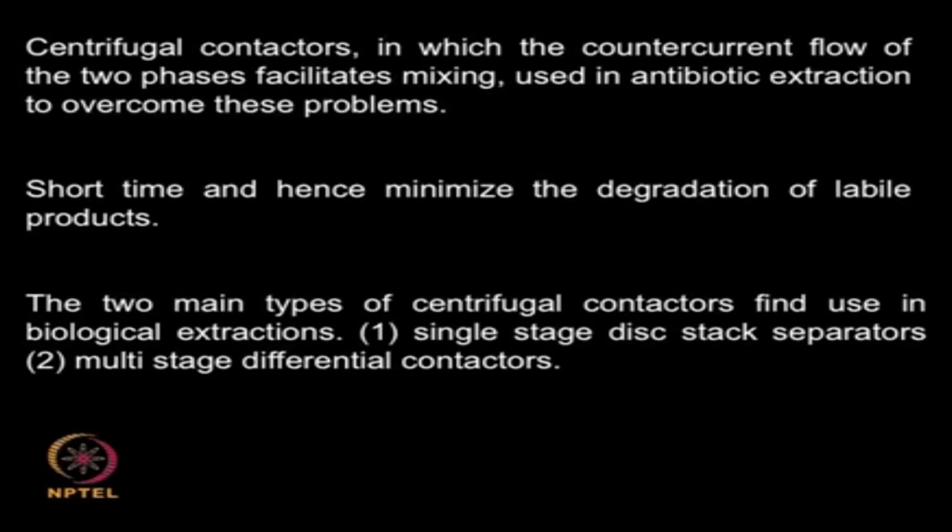So, if the density difference is very low, instead of resorting to the normal extractors which I talked about in the previous class, column extractors or agitated extractors, we may even go to centrifugal contactors. Nowadays there is a lot of interest in liquid centrifuges, where the normal centrifuge we are used to is a solid liquid centrifuge, where you are trying to remove the solid or filter the solid out using a centrifuge. But here we are talking about a liquid centrifuge, and the density difference creates the separation.